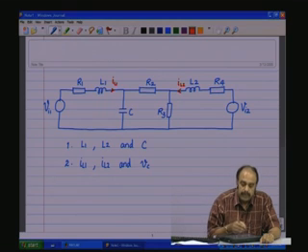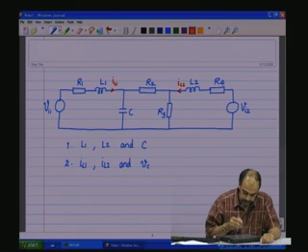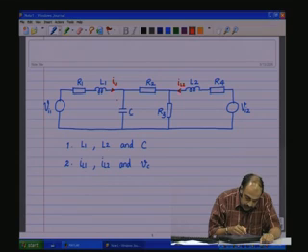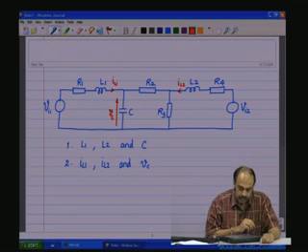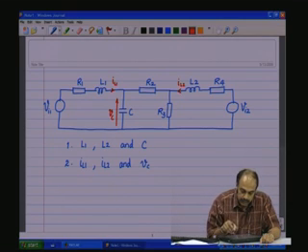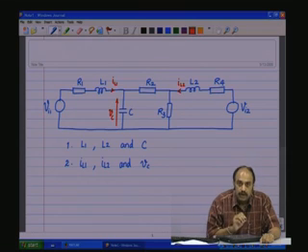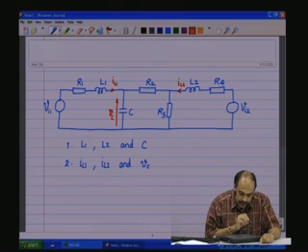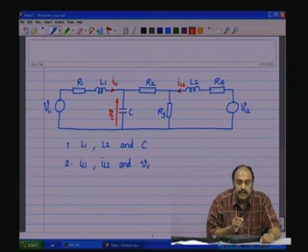The sign will automatically get changed in the equation and you will not face any problems as such. Now, the third state variable is the voltage across C, that is VC. So, now we have the state variables, the input variables and the parameters all listed on the circuit, and therefore, we should be able to obtain the state equations.